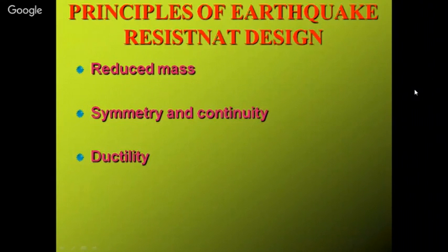In case of a masonry building, if there is an earthquake, first of all, in a masonry building you have one brick, after that a mortar joint, another brick, another mortar joint. So when the earthquake comes, first the cracking of the joint will happen. Because of that cracking and the small movement of the bricks, that is the damping. That is how the structure absorbs the earthquake energy.